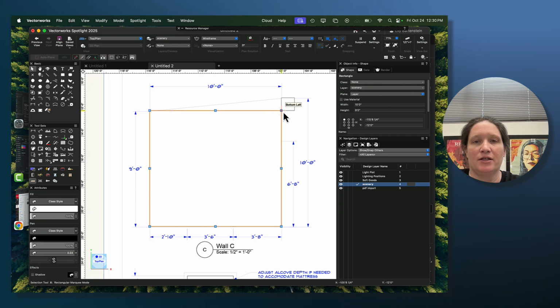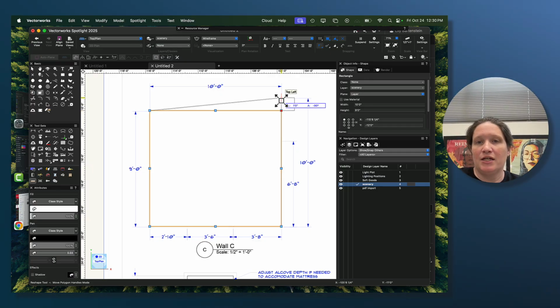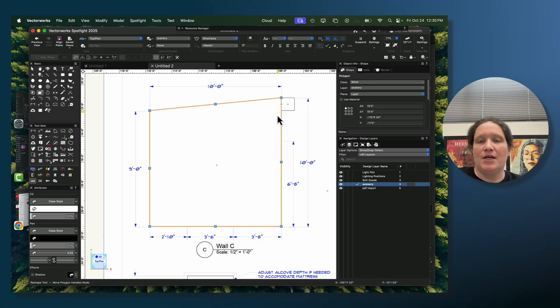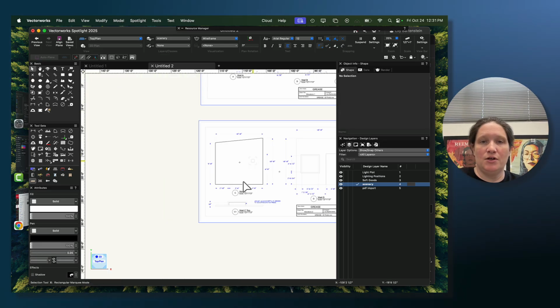When I click the first time, I get this draggy handle and the plus sign, which is the pick it up handle. When I double click, I get this handle with a box and 4 arrows in all directions. That one allows me to reshape. Because this is snapped into this corner, I can just reshape the edge of it. And now I have the correct height. So far, so good.